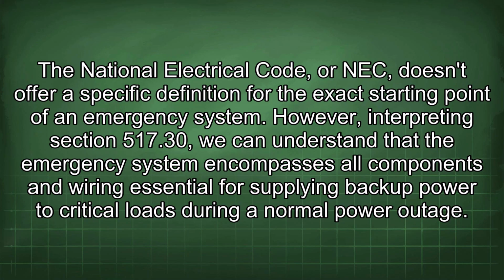National Electrical Code, or NEC, doesn't offer a specific definition for the exact starting point of an emergency system. However, interpreting Section 517.30, we can understand that the emergency system encompasses all components and wiring essential for supplying backup power to critical loads during a normal power outage.